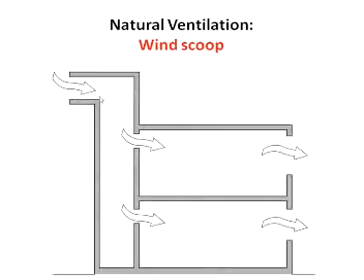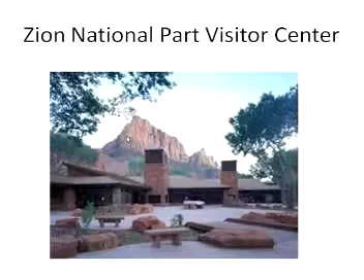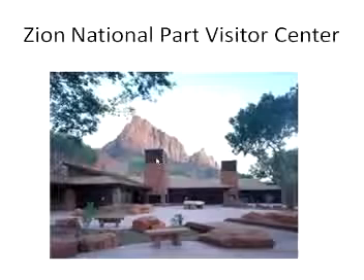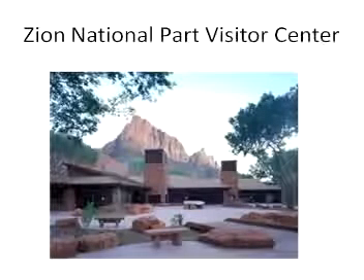In many of the cases, they've also put various kinds of textile materials which are dampened with water in here to provide evaporation. The evaporation lowers the air temperature, and the air now being colder and heavier helps promote the motion of air through the building. Here's a modern use of this technique in Zion National Park, and there you can see these towers here. Same idea: water is evaporated in the towers, it lowers the temperature and raises the density of the air, which then flows downward in the towers and out to the visitor center to provide comfort conditions through the summer.